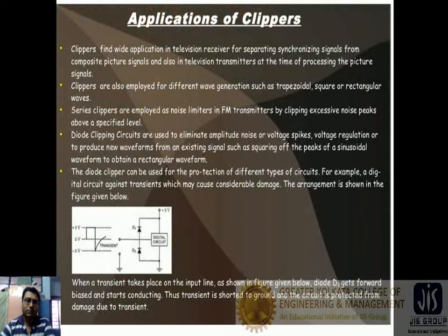Now let's come to the applications of the clipper circuit. Clippers find wide applications in television receivers for separating synchronizing signals from composite picture signals, and also in television transmitters at the time of processing the picture signals.